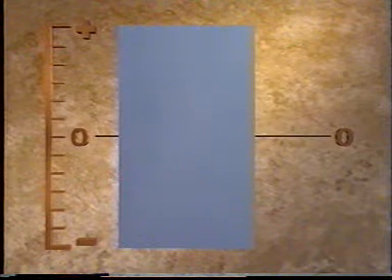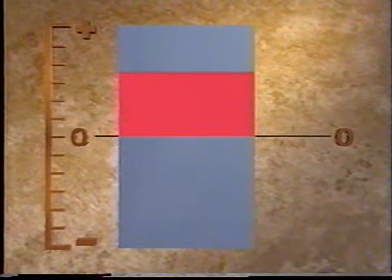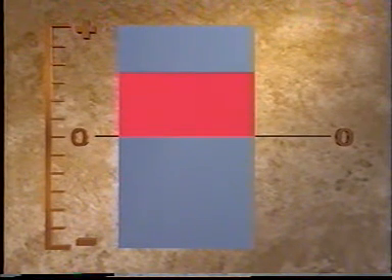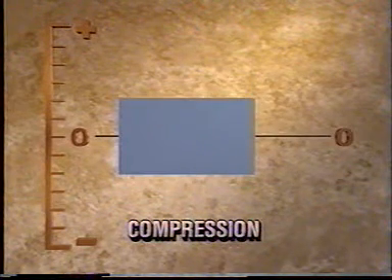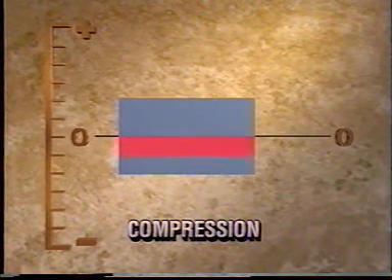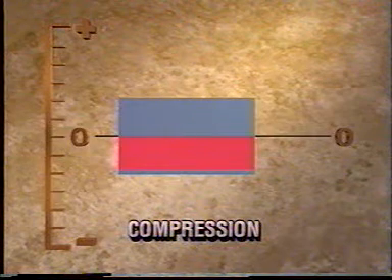The applied stress is uniform across the section, and the force is considered positive because the metal tends to become longer. On a graph, the tensile stress is depicted in a positive direction. When the applied stress is compressive, an action that tends to make the member shorter, the force is considered negative. Graphically, compressive force is shown in the negative direction. The stress, positive or negative, tensile or compressive, is uniform across the section of the member.